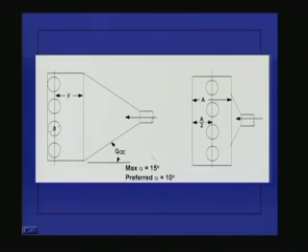What should be the spacing between the pumps, what should be the spacing between the wall behind the pump and the pump center line, what should be the spacing between the pump center line and this place, and what should be the distance between this inlet point here and the pump center line, and so on and so forth. There are guidelines available for this purpose.